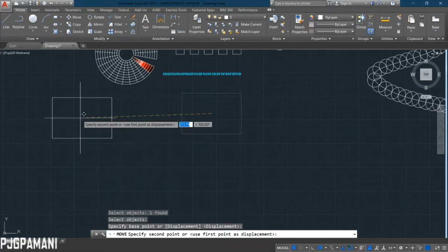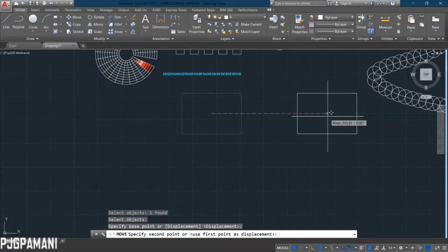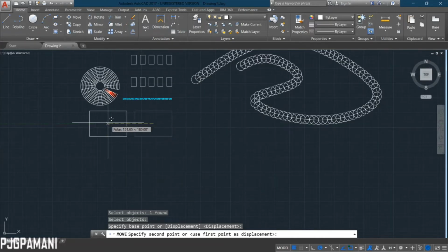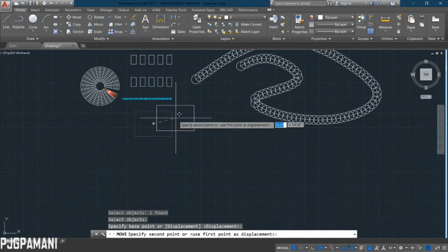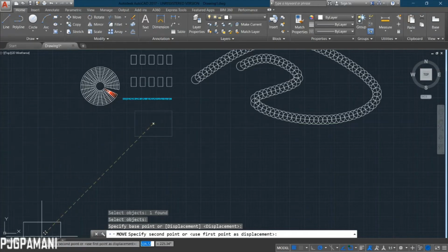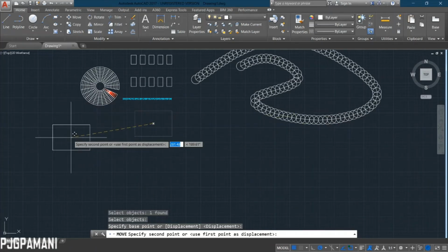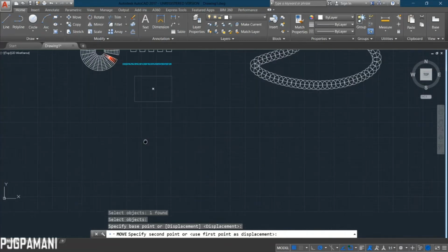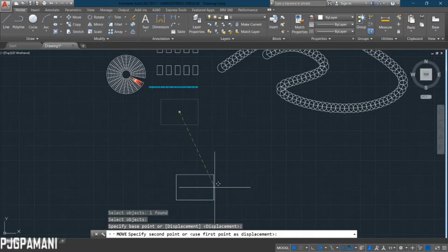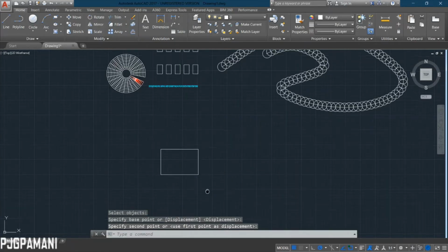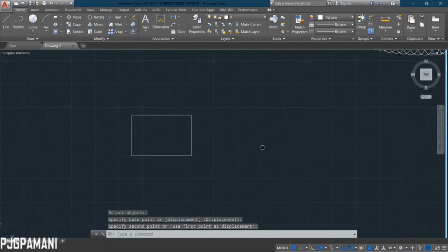If I want to move it from the center, I could easily move this object to a specified intersecting point in my drawing. Okay? And the same goes with copying. If I copy this object using the center as my base point, I could simply make multiple copies, specifically for foundations, columns, beams, floor framing plans, multiple input drawings, and so on. So that is the Move option.